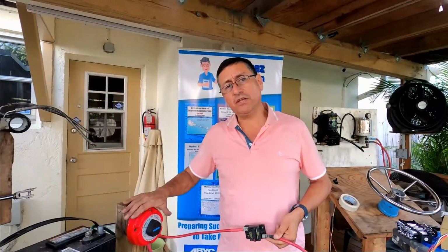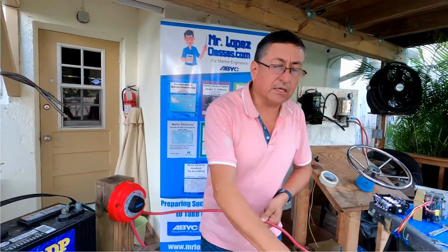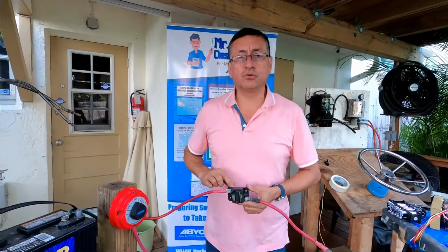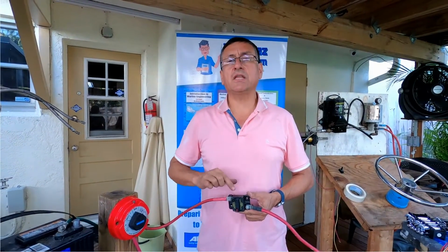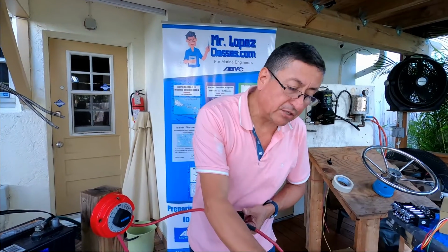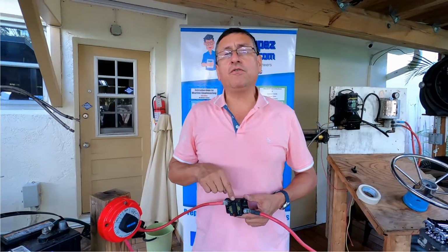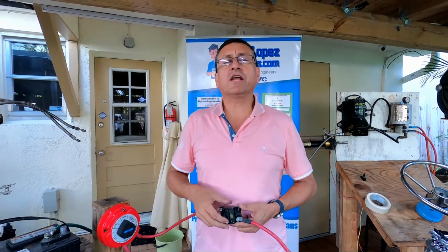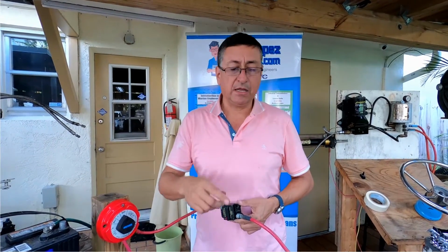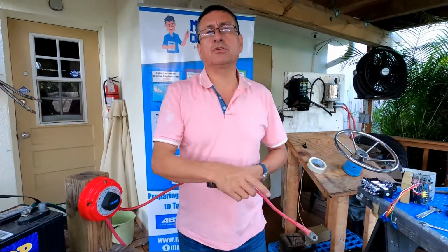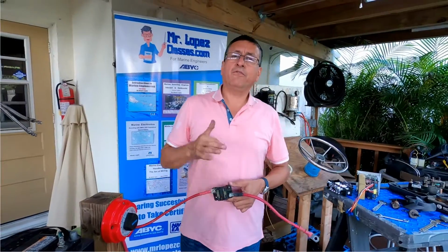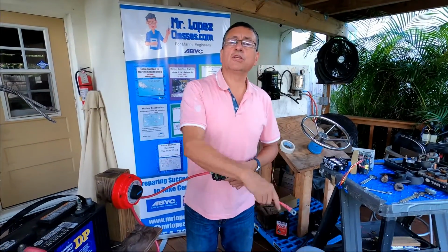The capacity of this selector should be higher than this. The same as the fuse. I recommend installing a fuse according to the capacity of that motor. The capacity of the fuse is always recommended by the manufacturer in the manual. The manufacturer of the bow thruster recommends what type of fuse is appropriate for this motor.